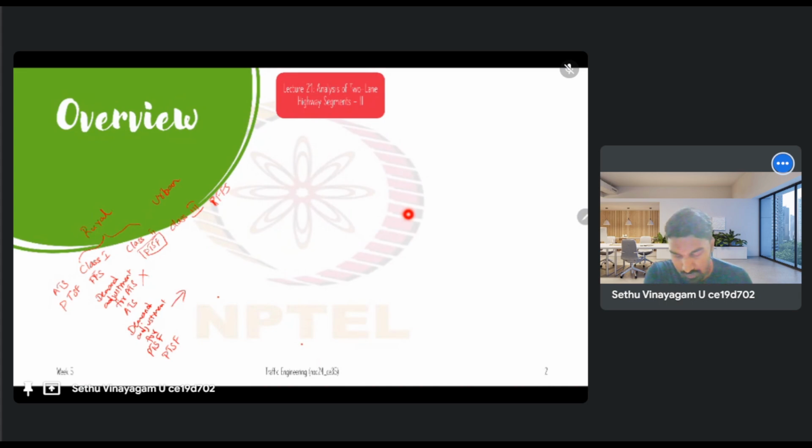Here we still need to estimate the free flow speed, because finally we are looking at a percentage of FFS. Once we get the free flow speed estimate, we go for the ATS determination, so we have to do the demand adjustment for ATS. Why are we calculating ATS? Because the calculation of the percentage free flow speed involves ATS. It is basically ATS by FFS that gives you the PFFS. To get the percentage of free flow speed, we need an estimate of the average travel speed. Therefore, we need to find the ATS.